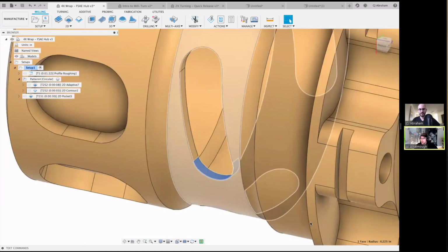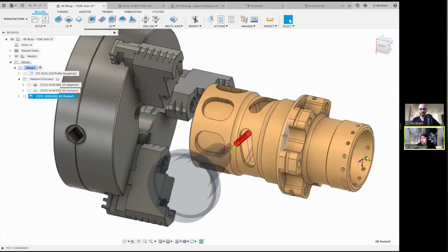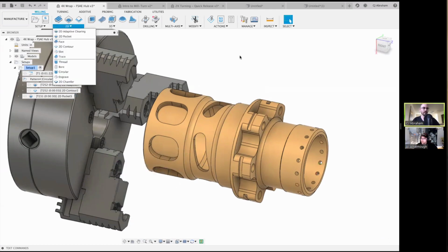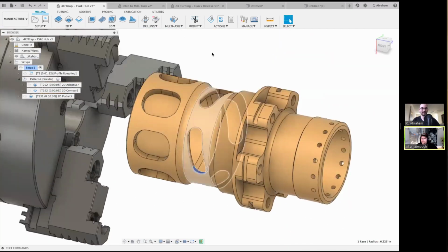Yeah. So that was a radial toolpath that was positional. Can you now do the wrap toolpath on the pocket? Yes. So, oh, by the way, I figured out the problem. It's because this slot is smaller than a half inch. Yeah. So the half inch tool never would have fit.